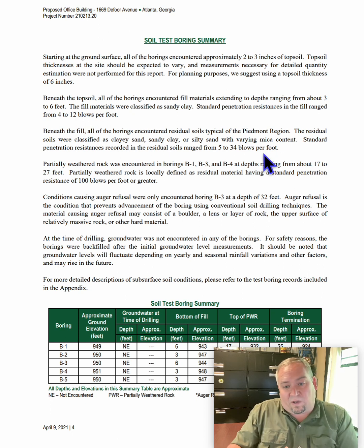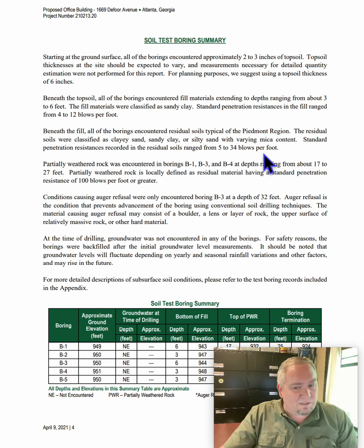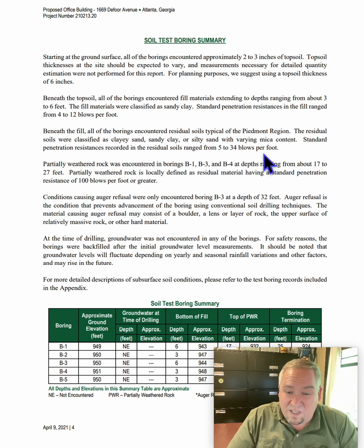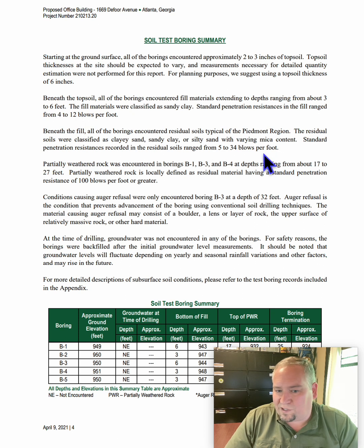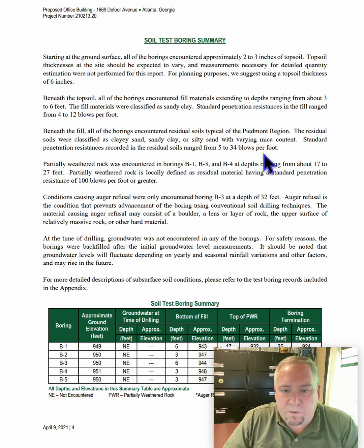And this will help you as a foreman or an operator be predictive and say, how long is it going to take me to load these trucks? Well, my blow counts are in the 25. That's pretty tight stuff. And I know once I get down to this elevation, I've got PWR close by. So you can be talking to the GC, you can talk to the foremans, guys can communicate and really set expectations so that you're not pushing your schedules behind and going, oh, we're going to be done in 2 weeks, and it's actually another week and a half after that. This will help you do a predictive analysis.